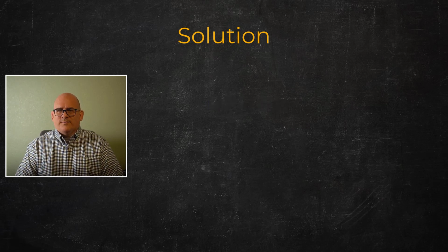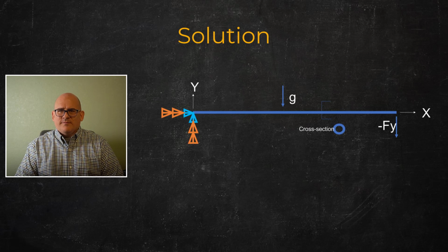One way to perform a multi-load case model is to issue the SOLVE command multiple times with the appropriate loading commands necessary to define the loading environments. For example, in a static structural model, we may wish to consider only the effects of gravity first. Then in a second analysis, we may want to add working loads in addition to gravity.